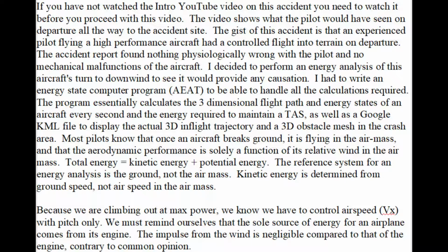I decided to perform an energy analysis of this aircraft's turn to downwind to see if it would provide any causation. I had to write an energy state computer program, AEAT, to be able to handle all the calculations required. The program essentially calculates the three-dimensional flight path and energy states of an aircraft every second and the energy required to maintain a true airspeed, as well as a Google KML file to display the actual 3D in-flight trajectory and a 3D obstacle mesh in the crash area.